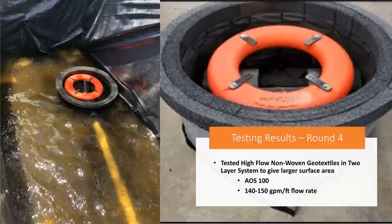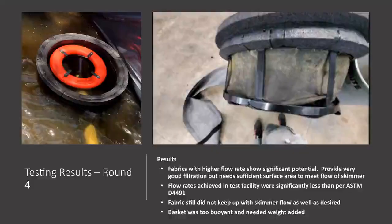For the fourth round, we tested a high-flow, non-woven geotextile in a two-layer system to give a larger surface area. We built a basket to hold the material away from the skimmer. It had an AOS of approximately 100 and a flow rate of 140 to 150 gallons per minute per square foot. So our results with this system were better. The fabrics with a higher flow rate were showing significant potential. They provided very good filtration, but it needs sufficient surface area to meet the flow of the skimmer.